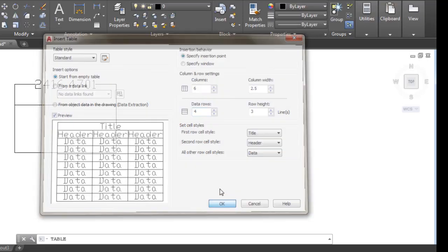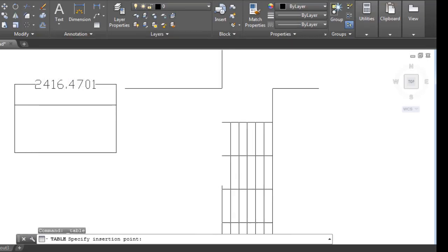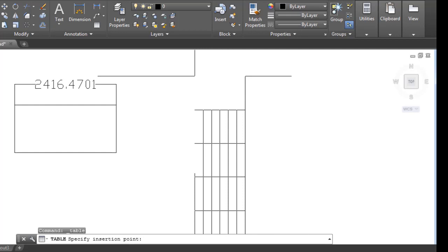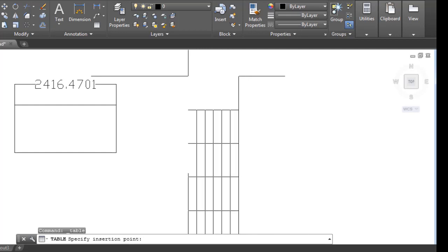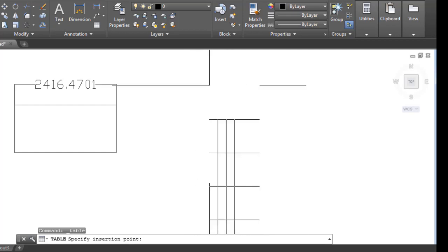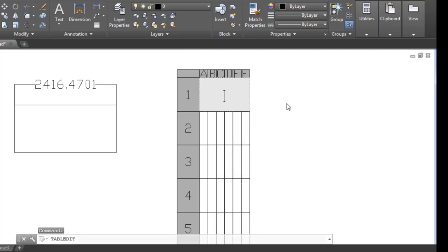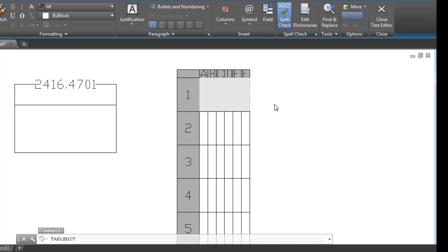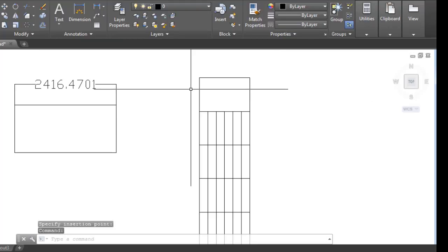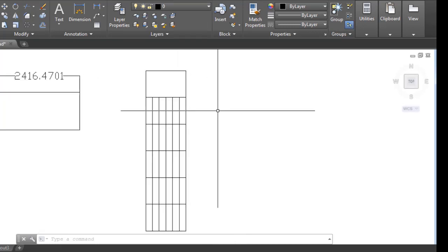You can see that even without dropping it, the table has appeared. Now you drop it wherever you want to put it. You left click again to drop it. By the time you do that, you left click again, or you enter. And what I want to let you know is that left click again can also mean the same thing as enter and spacebar in AutoCAD.